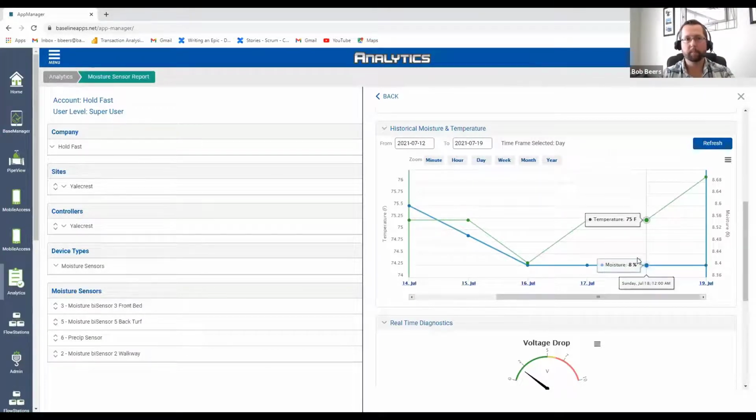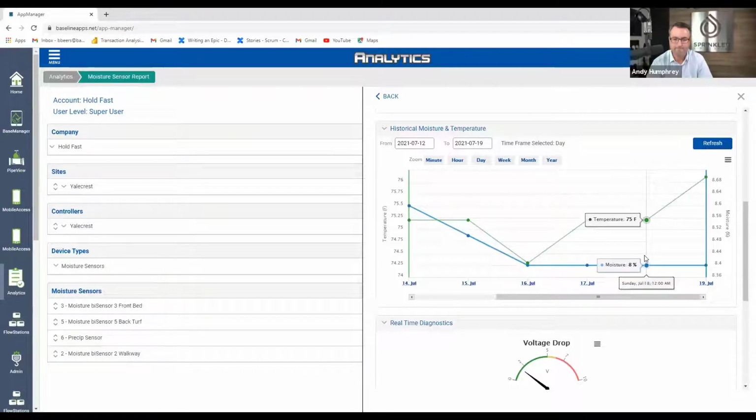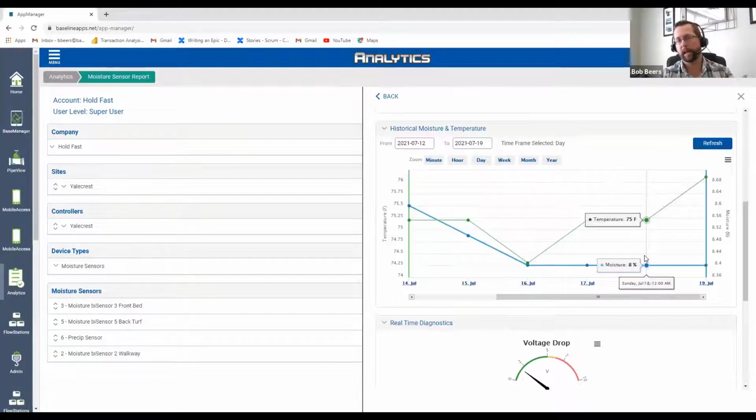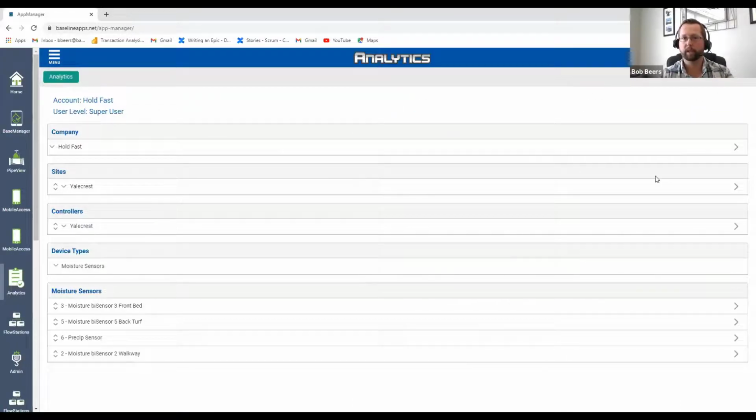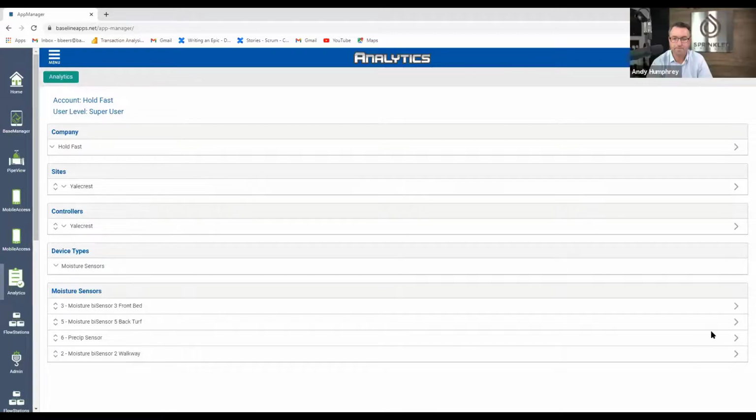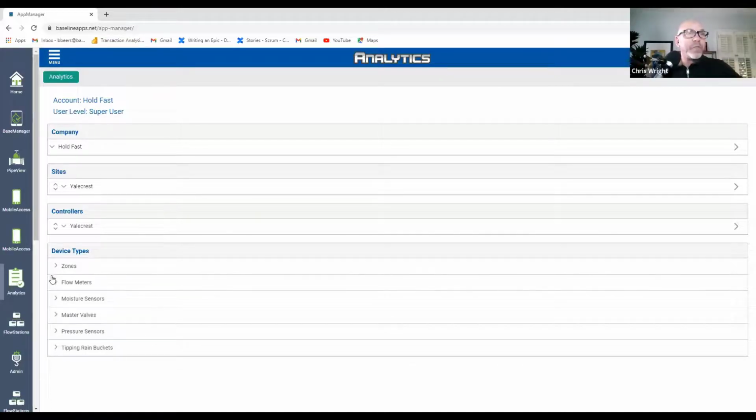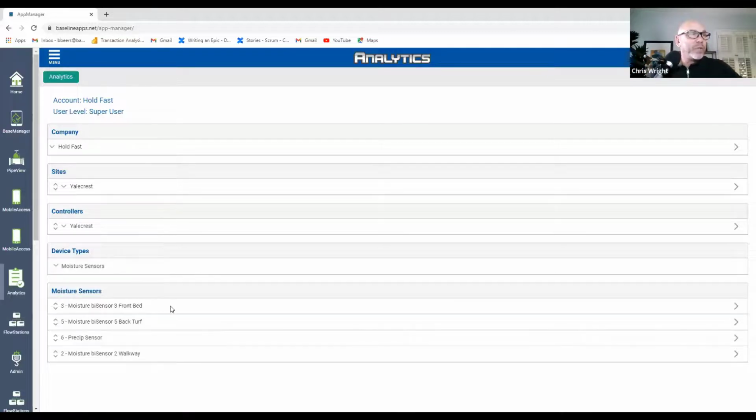So my company used more water this year than last year. Why? And then being able to look at an individual soil moisture sensor at that HOA, and then look at the actual soil profile temperature and see year over year, this is what I measured July 18, 2021, and here's where we were July 18, 2020. We're 3 degrees higher. Right. Yep. And that's actually what really matters: the air temperature is one thing, but it's how the air temperature affects the soil temperature. Right. Exactly. Helps us understand how evapotranspiration is happening in the landscape in real time.